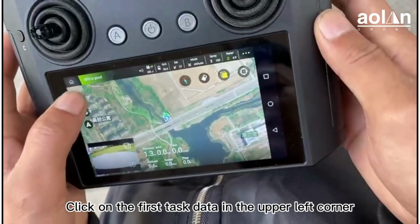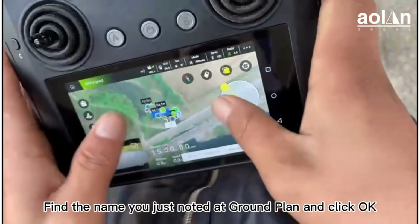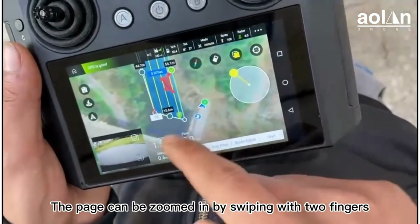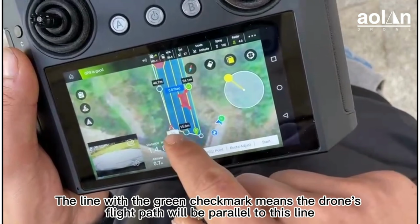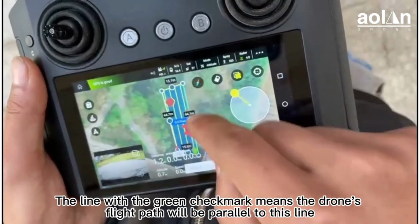Click on the first task data in the upper left corner. Find the name you just noted at ground plan and click OK. The page can be zoomed in by swiping with 2 fingers. The line with the green check mark means the drawing flight path will be parallel to this line.